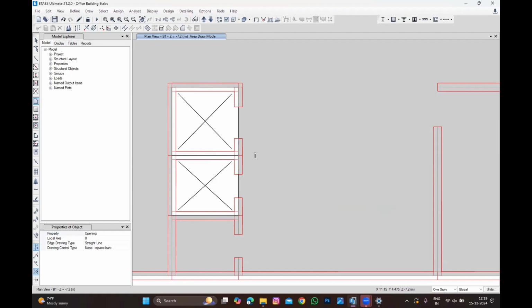You don't need to, actually, because you're making it complicated. In any case, it remains the same: we just transfer the load to the walls, right? We're only transferring the load to the walls. We're not going to design this category; we are only transferring the load. If you model the landing and base slab as an incline, you're making it complicated. At the end, the loading is going to transfer to the wall, rather than just modeling it as flat.